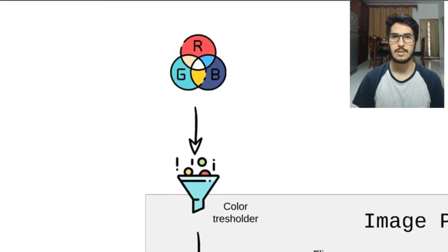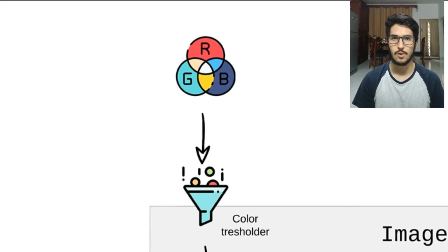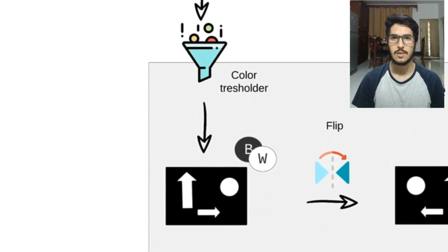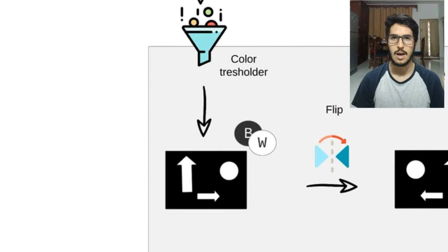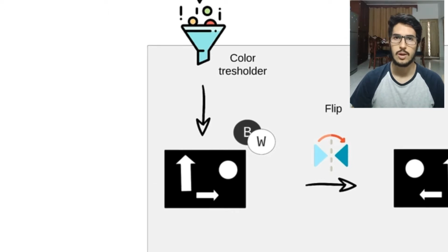Now we talk about the image processing subsystem. The image processing starts by separating the red, green, and blue channels of the image, which are processed by a threshold filter that allows identifying the path the drone has to follow, based on the colors of the track. Then the filtered color components are merged in a new image that is finally converted into a binary image. This filter is based on the color thresholder app provided for MATLAB to allow its easy calibration mode in a real environment.